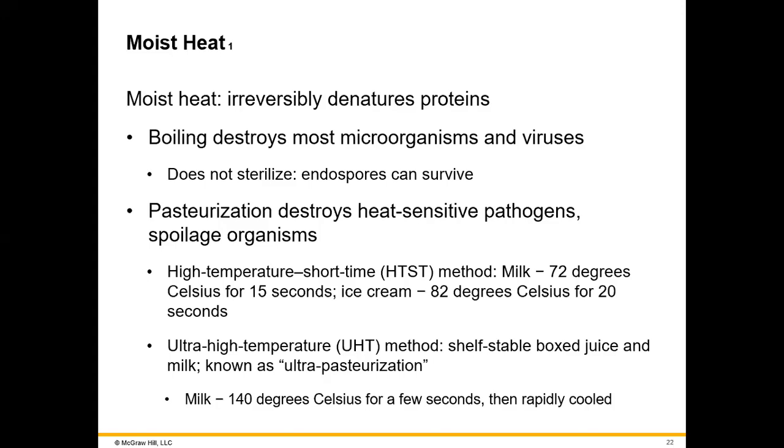to achieve pasteurization. So what they do, they pass the milk through pipes. The pipes are surrounded by a wire with resistance, meaning that it gets hot, and the resistance is controlled such that the temperature is around 72 degrees Celsius. And the length of the pipe is such that the milk passes through the entire pipe in a period of time of 15 seconds. So it comes out the other side, already pasteurized and ready for packaging in containers.